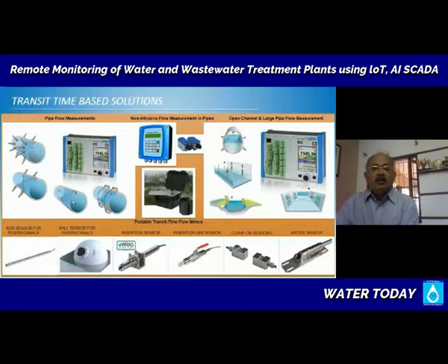On the right-hand side, you see how they show the measurement in a canal situation, where you are measuring the velocity with these sensors, and you are measuring the depth through either an embedded sensor along with the velocity sensor, or a separate level or depth monitoring sensor. All of these are shown at the bottom as well, showing once again how you can have varied technologies and varied sensor configurations that are available for you to acquire your water data.